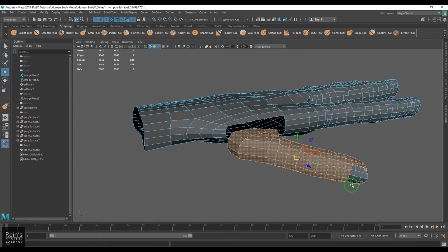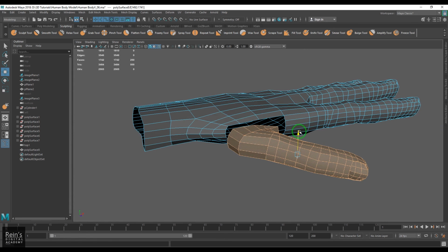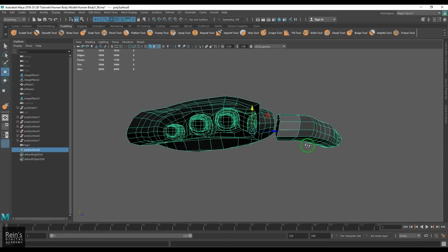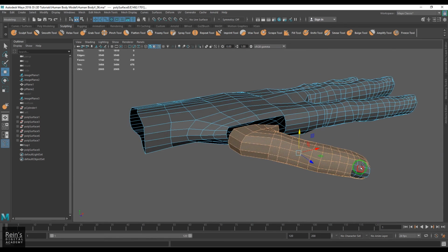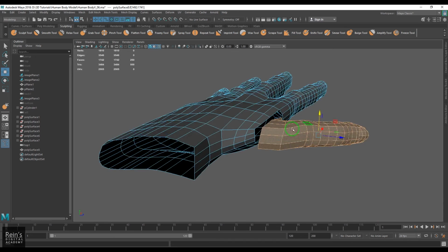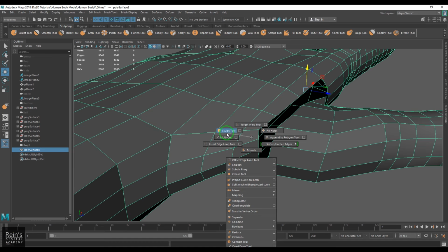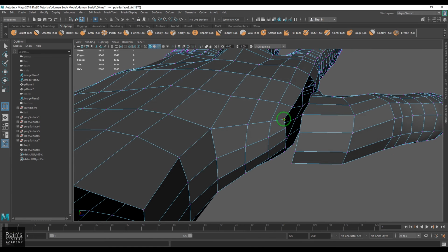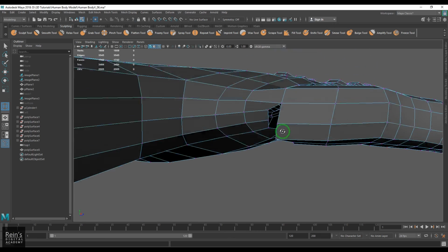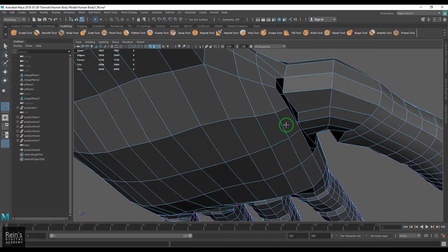When you double click any model, that small group of model can be selected, because generally it's one piece, so I can't move it in object mode. So double click and then that will be selected like that. So start connecting them. Okay, let me select one of the vertex and then choose the target weld tool and start connecting the lines and see what all lines I have to add or delete.